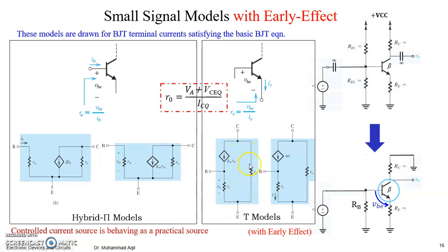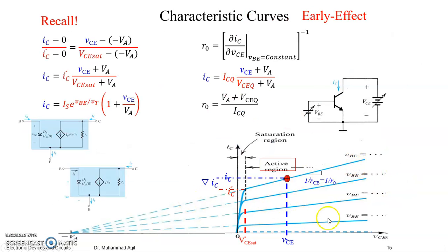So it means the collector-to-emitter dependence on IC. Obviously, we already know that, we are just repeating, it depends on where your Q point is. And obviously it depends on your early effect, which is common for all the curves. So how much current there is, divided by this value, depends on where your Q point is. This one is the delta change. So you are here now. If your Q point is here, you are actually this much away, so you have to add this factor, which depends on this and the early effect.